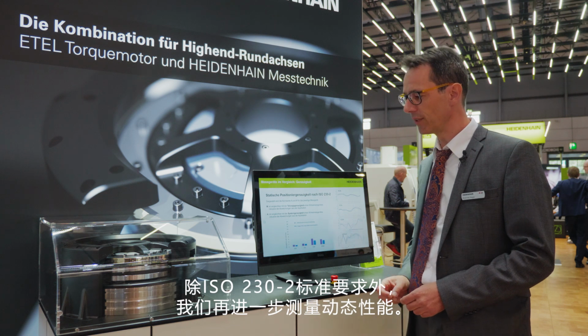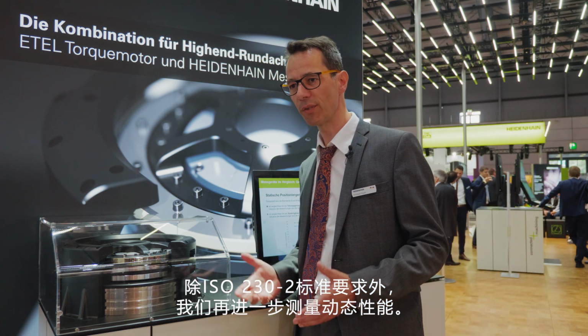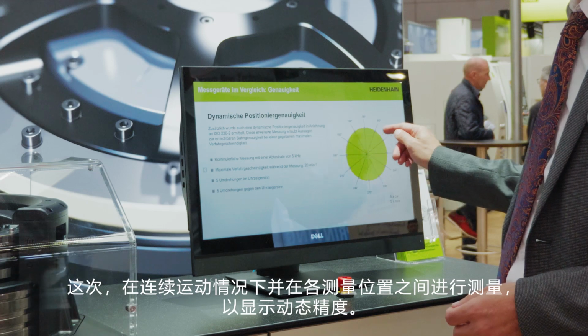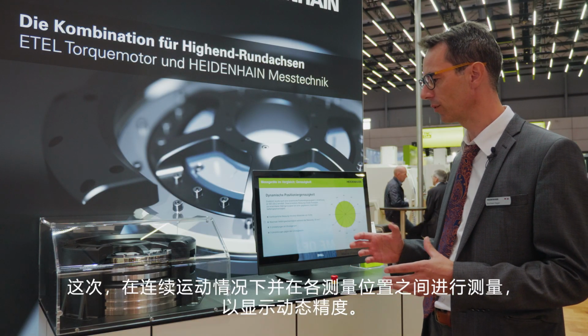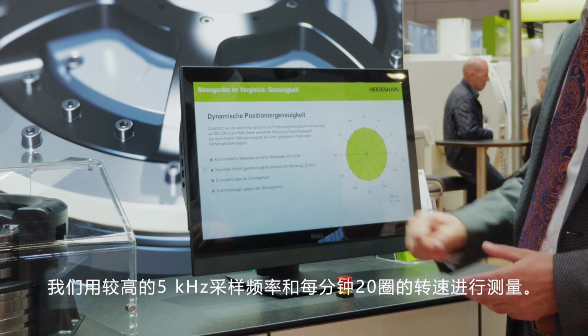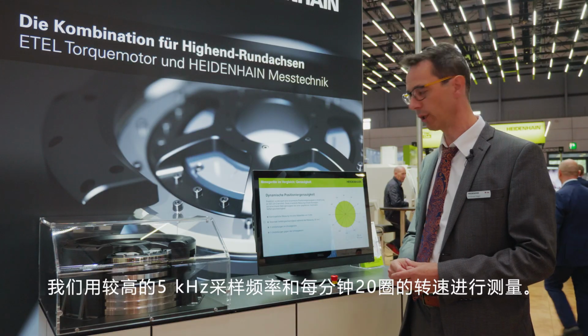To supplement ISO 230-2, we are also performing a further measurement of dynamic performance. This time we measured between the individual positions under continuous motion in order to show the dynamic accuracy characteristics. We measured at a very high sampling rate of 5 kHz and a speed of 20 revolutions per minute.